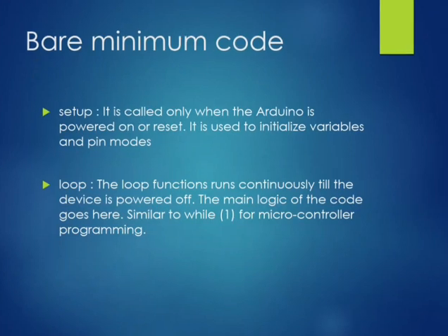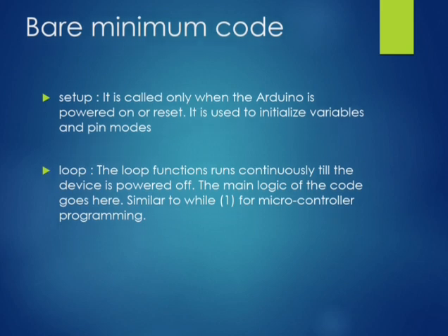Setup is called only when the Arduino is powered on or reset. It is used to initialize variables and pin modes. Loop: the loop function runs continuously till the device is powered off. The main logic of the code goes here, similar to while(1) in microcontroller programming.